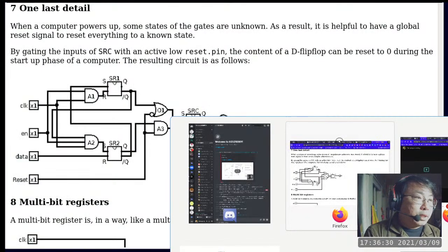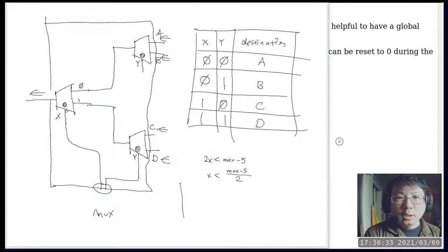So now we are going back to the multiplexer versus a demultiplexer. The only difference between those two is really just the direction. A demultiplexer has one single input and multiple outputs. And a multiplexer is like what this diagram has here, which is multiple inputs and only one single output. The job of a multiplexer or demultiplexer is really just acting as a switch. It's basically saying which point connects to the single input or output.